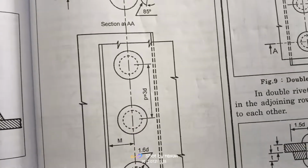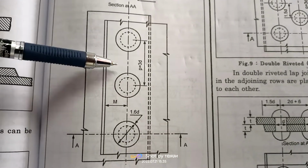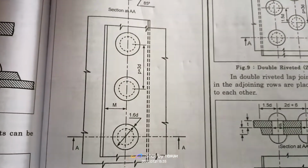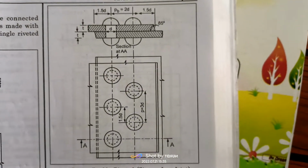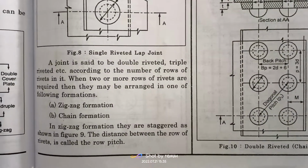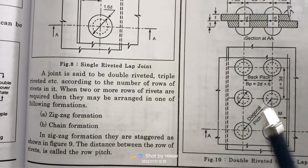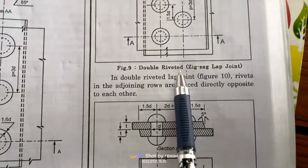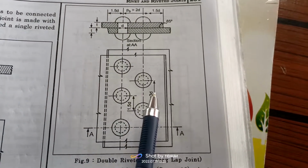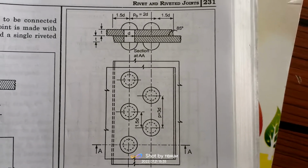Now the distance between the two rows of the rivets is known as pitch. There are two types of riveting here: one is zigzag formation and one is chain riveting. So this is our zigzag design. One rivet is here, then here. This is the zigzag design, and this is a double riveted lap joint.